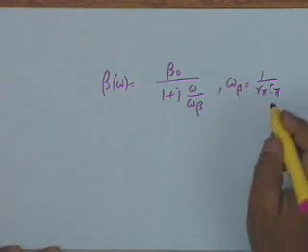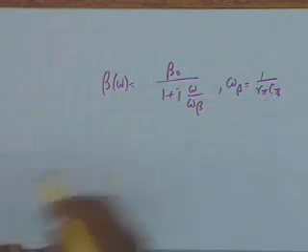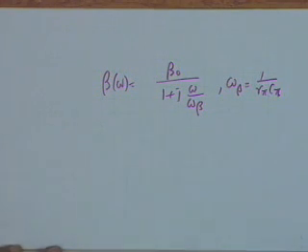If you want for your design the given F beta, you can find out C pi from there because you know R pi. How do you know R pi? R pi is beta 0 by GM. How do you know GM? 40 IC. And beta 0 is specified by the manufacturers. They specify beta, they don't specify R pi, they do specify omega beta. Sometimes, most of the times, manufacturers do not even specify omega beta.